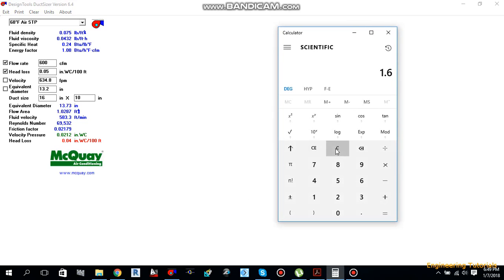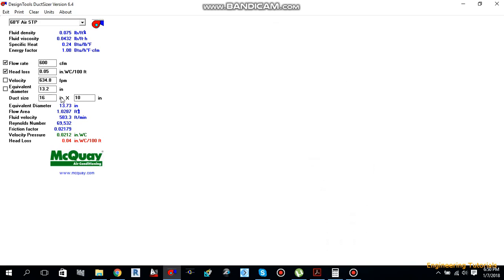So what would be the aspect ratio in that case? 400 divided by 250, that is 1.6. So aspect ratio is good, no problem. But sometimes you have to play with this aspect ratio because of the ceiling height issues. Sometimes ceiling height is very low. Let's say the ceiling height is 500 mm. So you will keep your duct height maybe restricted to 200 mm or 250 mm,